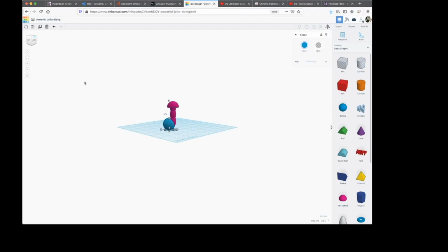This is one thing that can be tricky when you're manipulating shapes in 3D software. You can lose where they are until you kind of get used to understanding the space visually, right? So it's important to use the little navigation widget to help you make sure that the shapes are in the proper place in space, right? Okay, so I'm going to go to maybe the front view,